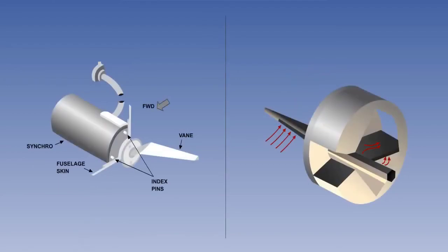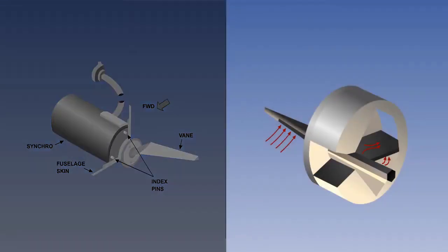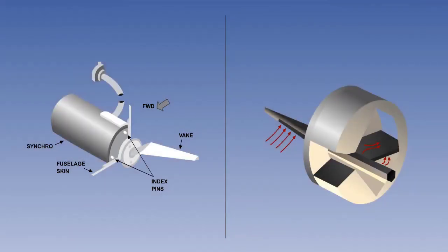As previously mentioned during the components phase, we are now going to learn about the angle of attack sensing probes. They are positioned on each side of the forward fuselage with two basic types in use: a vane type or a conical slotted probe. Both are protected against ice formation by a heater.